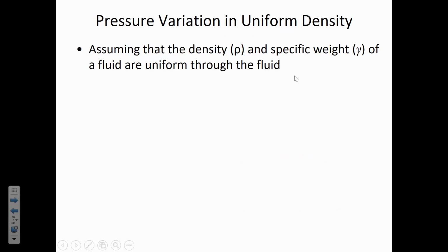That's the general relationship, and there are a few things that we have to keep in mind when we do problems related to going down into a fluid, pressure variation type problems. We'll assume that in fluids the density and specific weight is uniform, and that's a pretty good assumption for liquids. It's a less good assumption for gases, atmospheric gases, because if you go up in the atmosphere, the density of air is decreasing.